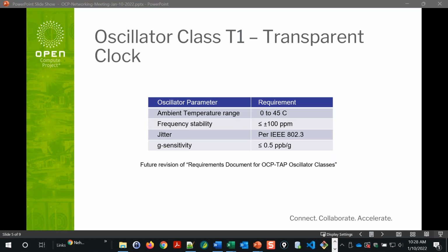Yeah, and I think it's the second path that we've been leaning on, in the sense that most of these requirements, like frequency stability, are a pretty standard thing in the industry, and everybody's probably fairly responsible for measuring it correctly. But other areas like holdover, there's just a wide variety of methodologies and ways of reporting, particularly when it comes to statistics, because wander is a statistical noise process, and how do different vendors account for that? Is it 1 sigma? Is it 3 sigma? Is it 6 sigma? That never shows up in a data sheet nor application notes or white papers. So for those areas where there's some variability, we like to define the methodology. But for the others where it's fairly consistently done throughout the industry, there doesn't seem to be a need for that. That's fair.